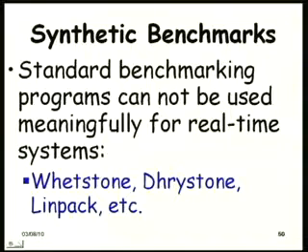the manufacturers optimized their system with respect to this benchmark, because they know finally they will have to quote with respect to a Whetstone or a Dhrystone benchmark, and the source code of these is available.